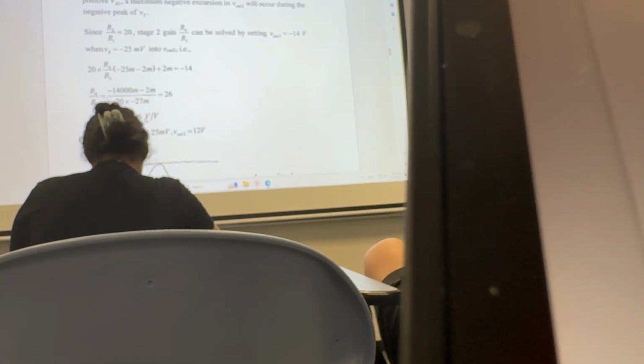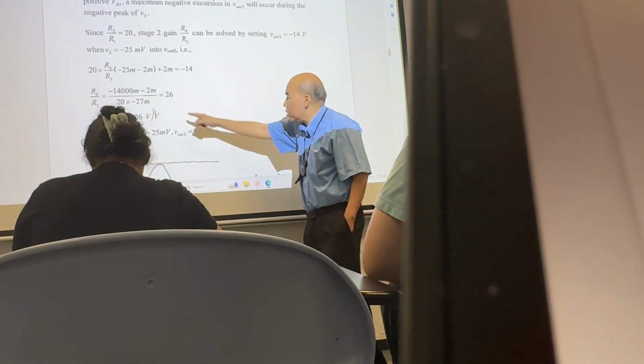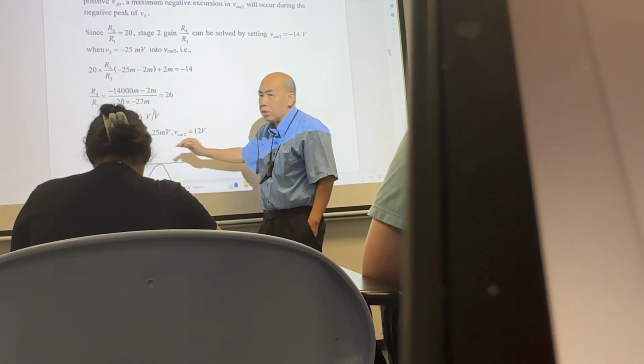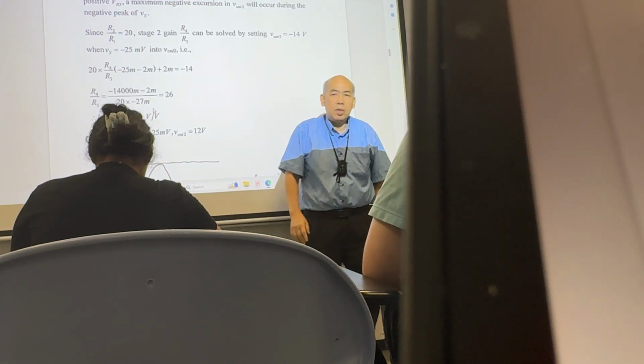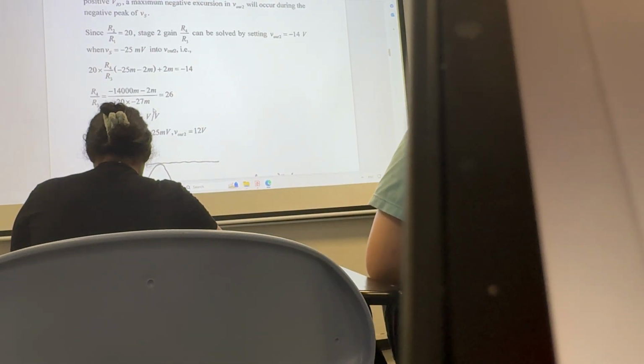You solve this expression, you will find that this is minus 26. Okay, minus 26 is a limit. If you check the minus 25 positive for the design equation, you have a subtraction. That means you will not saturate, right? Only 12 volt. So the answer is you have to look for the worst case, right? From the offset point of view.